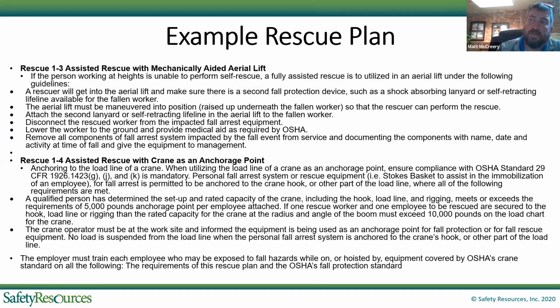And then the other one that we see that has happened, I have been involved in this, and OSHA has challenged us on this. But in a rescue situation, you can use whatever means necessary. And so if you need to use an assisted rescue with the crane, getting the headache ball to wherever it needs to be, this is for our bigger projects, you can do that. It just really needs to be well thought out and planned, and folks need to be at least trained on it.